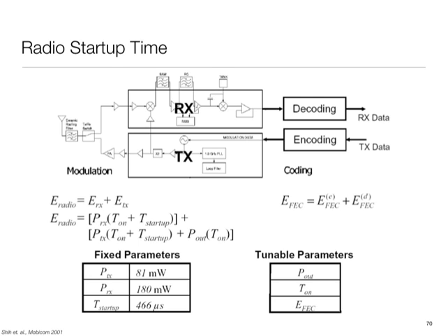So this slide is showing the bottleneck that a radio can become if its startup time was not optimized. Starting around the 2006-7 time frame, this came into consciousness, and several radio protocols that have emerged since are explicitly optimized for the receive side and for rapid wake up. Whereas if you go to cellular, they are really catering to long distance, and their focus has been on making long distance transmission efficient, namely focus on the distance dependent term. And the way they do it is by coming up with better and better, more efficient codes, because codes basically give you an energy gain out there.